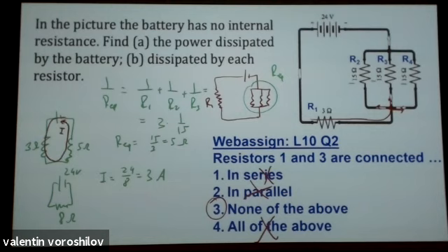Actually, in this circuit, see, from plus back to minus, electric current travels counterclockwise. Here it travels to the left, and here it travels up. And well, here it splits. How? Evenly. For same resistors, electric current splits evenly. So it's going to be I over 3, I over 3, I over 3, which gives 1 amp. Then it combines again into 3 amps.